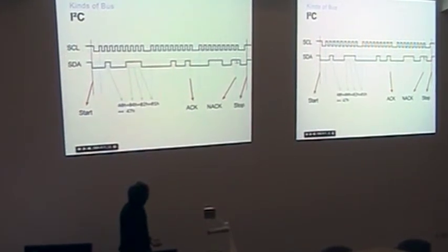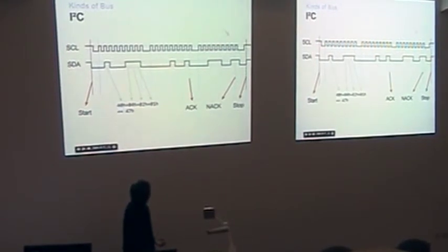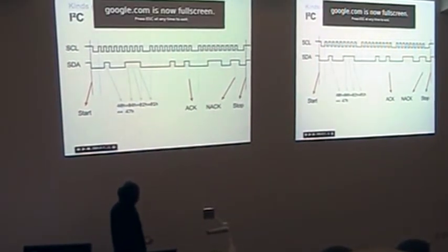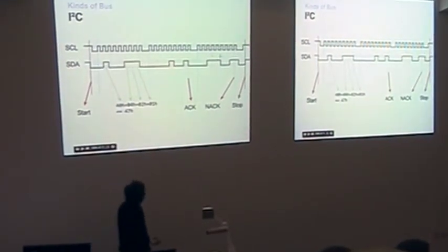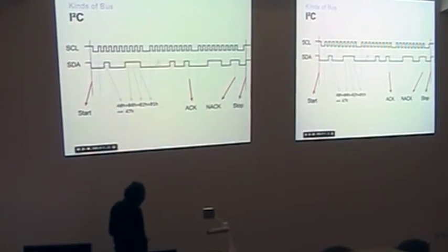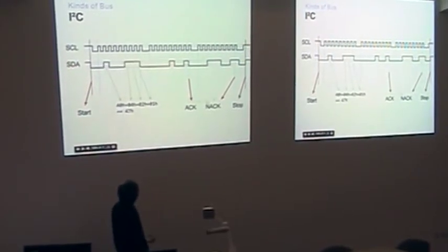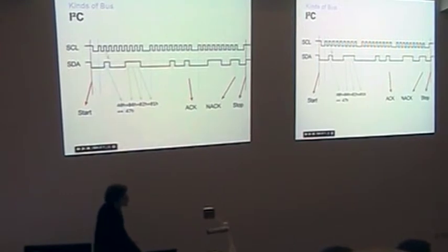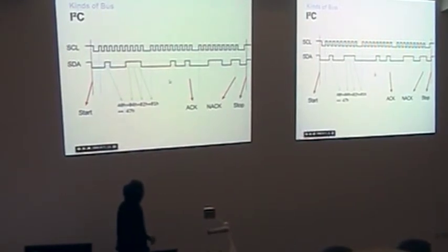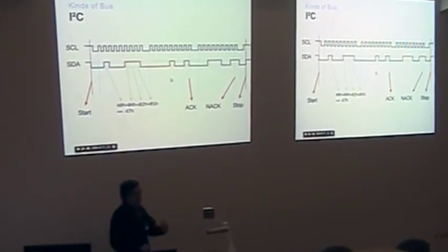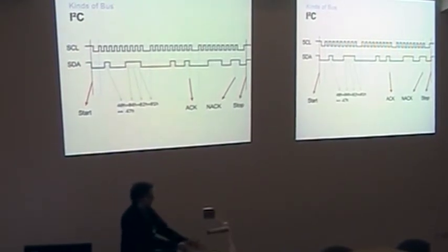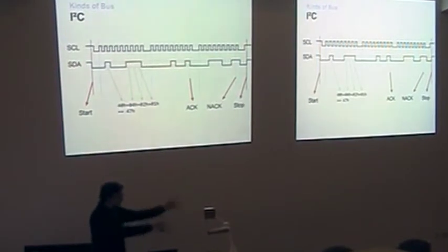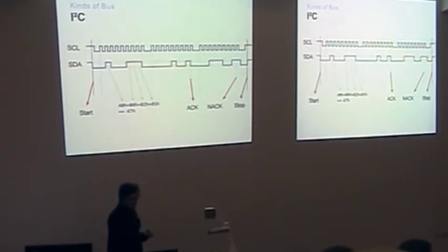And this one over here decided to let go of the line because for some reason it's finished, it's had enough. At which point we stop. So there's this slightly more complex, weird protocol going on, where you have starts and stops and the ACKs and that. You can send read writes and write bytes, all the complicated stuff. So it starts to get tricky if you're going to type it all onto that little text interface, when you're just trying to talk to a temperature sensor or something. You just say, I want to read the temperature, don't complicate me with all these fancy details.